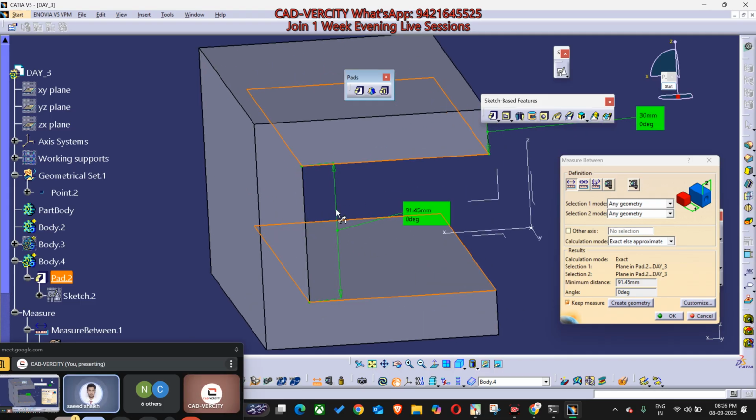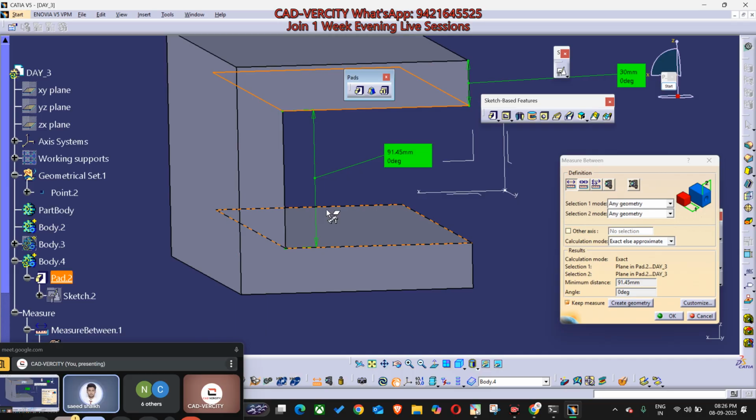Will it not be in the constraint option, sir? No, thickness, no, no. We are in 3D now, Part Design. We are not in sketch here. Is this like the constraint? No, not like constraint. In constraint, if you change the dimension, 3D will update. Here, we just measure the thickness, and also angles.